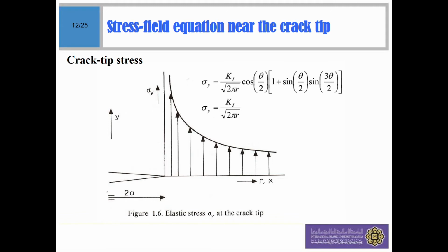Okay, in calculating the crack tip stress, it can be visualized with this graph. If I have a crack length of 2a, this is the crack length, while this is our crack tip. Based on this trend, the yield stress is at its maximum value near the crack tip, while if you take a far away location, it will be lower.